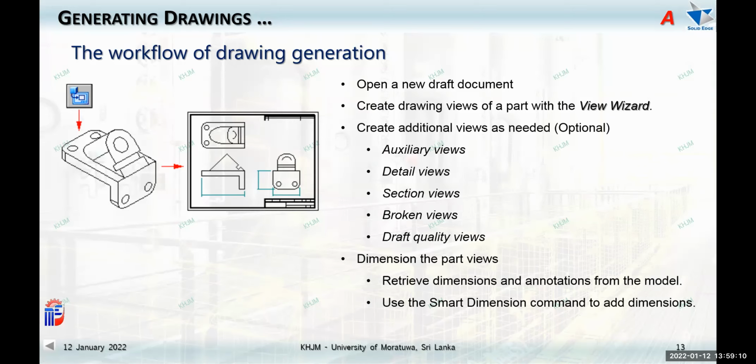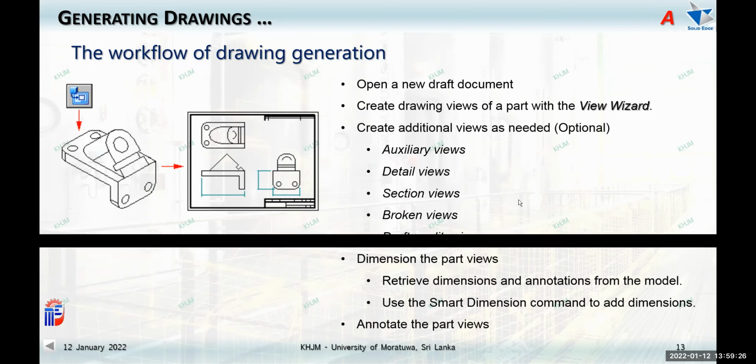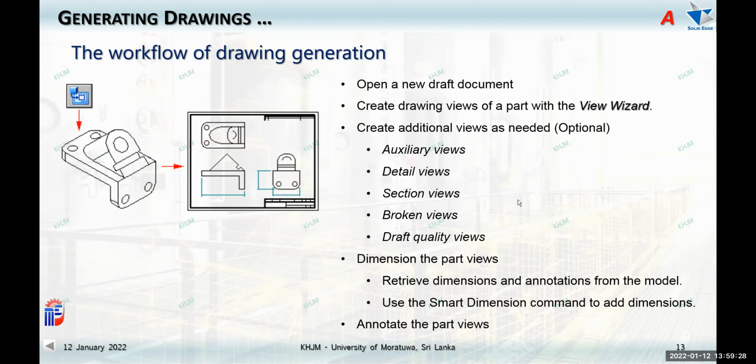So when you use the smart dimension tool to generate a dimension, sometimes it becomes driven dimensions. Because the dimension I did not extract, I was keeping that one, and then the new one becomes driven. If you use the smart dimension tool, then it becomes a driven dimension.